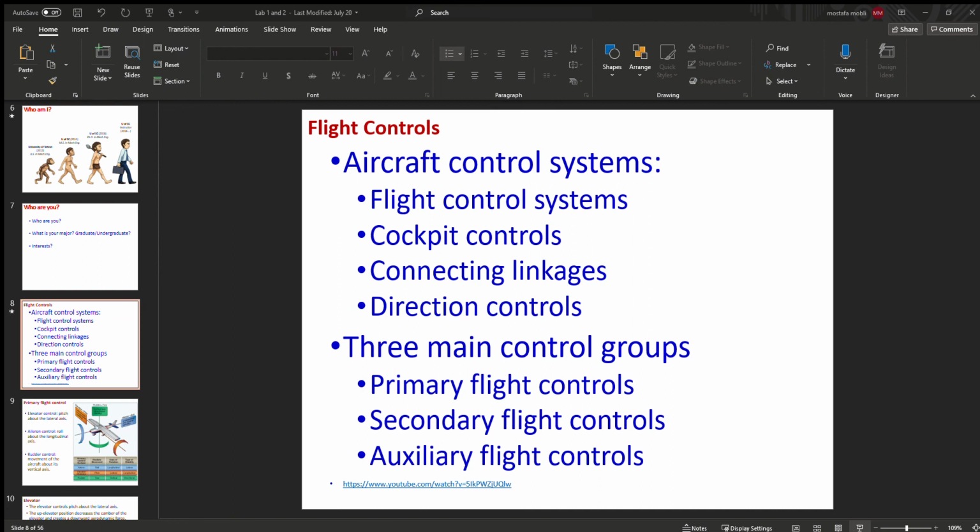The amount of rudder control required is highest at lower airspeeds and high angles of attack, because you have higher drag generation and higher adverse yaw at lower airspeed, higher angle of attack, and obviously at larger aileron deflections.